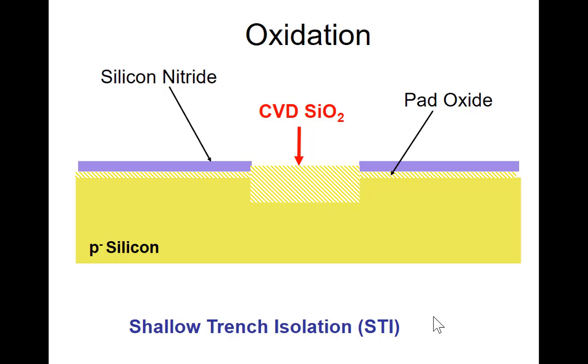So we know that in semiconductor processes, the lateral control is very precise, very good. So when we use this to make this trench, we can control this width very well, and it can be much smaller than the p-n junction depletion region for separating the NMOS and the PMOS transistors. As a result, you can put a much higher density of transistors with this shallow trench isolation. And this is after you deposit it.